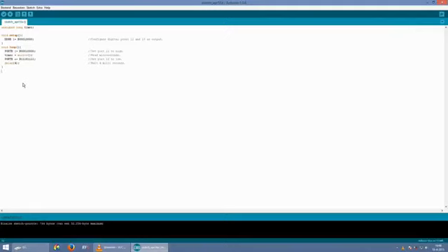Another thing worth mentioning is the time it takes to read the microsecond value. I use this line as an example. As already shown, the pulse takes 200 nanoseconds without extra program lines. The extra pulse length is created by reading the microsecond timer. Now let's upload.